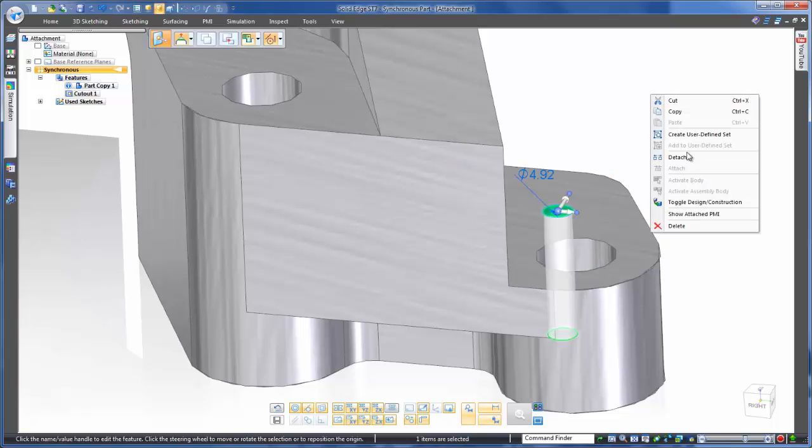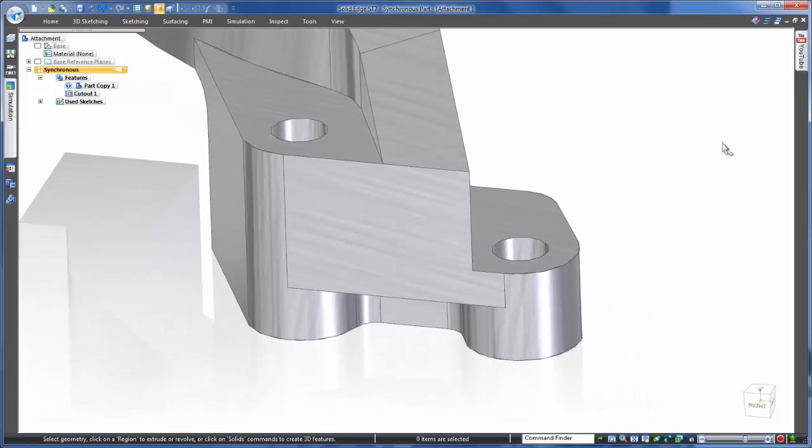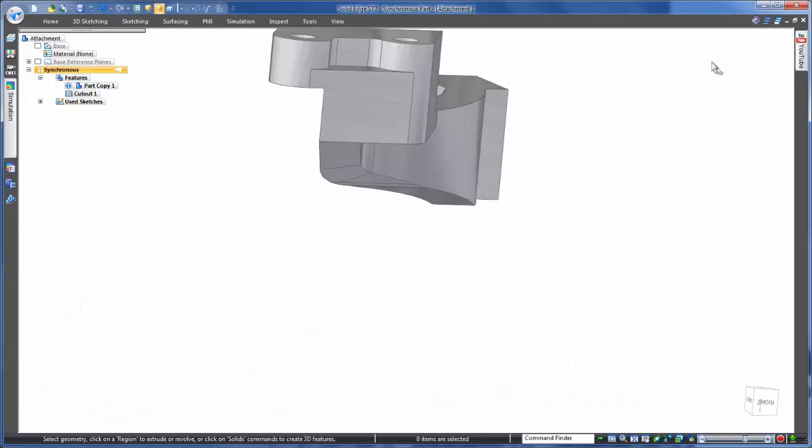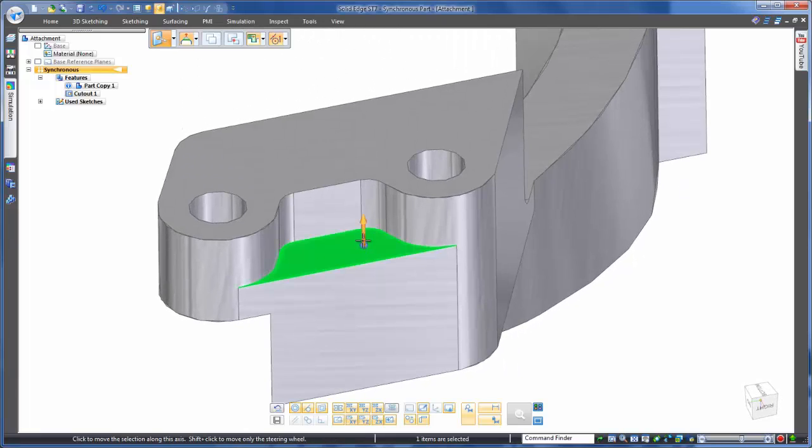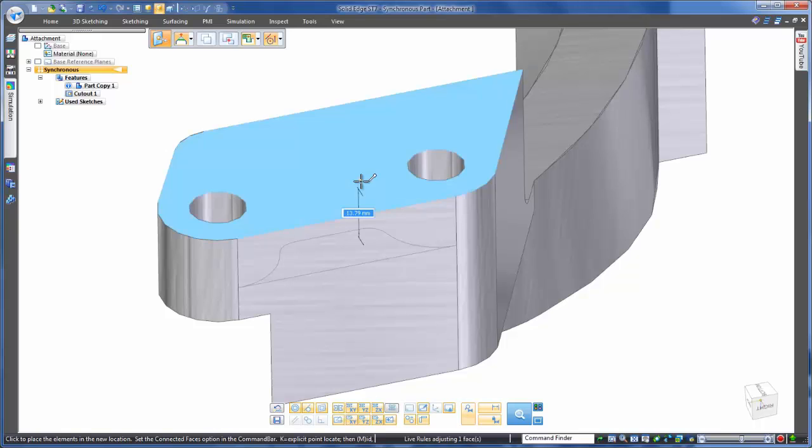Notice every time we delete, Solid Edge patches the model up for you instantly. What about any geometric edits you might want to make? You don't need a history tree for this. Simply click on the face to drag and snap.